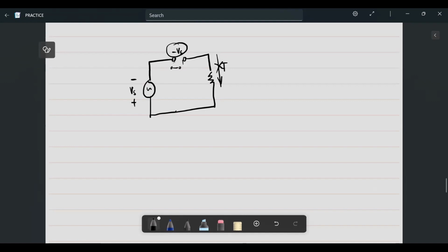But the real diode doesn't behave like a short circuit. It has a very small voltage drop, of about 0.7 volts if it's a silicon diode. But when it's in reverse bias, the voltage that appears across it is equal to the source voltage, and that voltage is called the peak inverse voltage. So what should be the rating of the diode itself? It has to be at least the value of the source voltage, Vs.